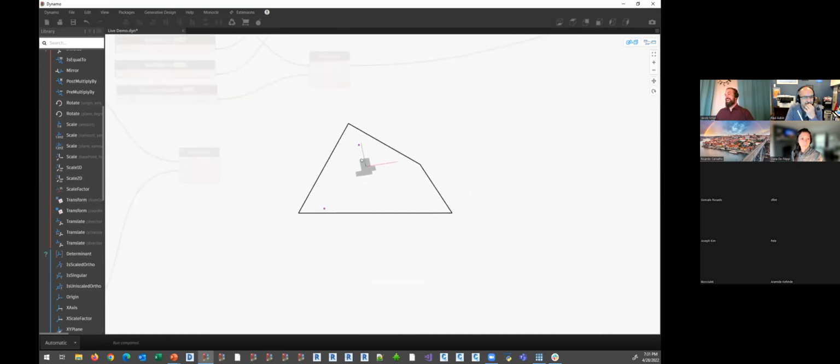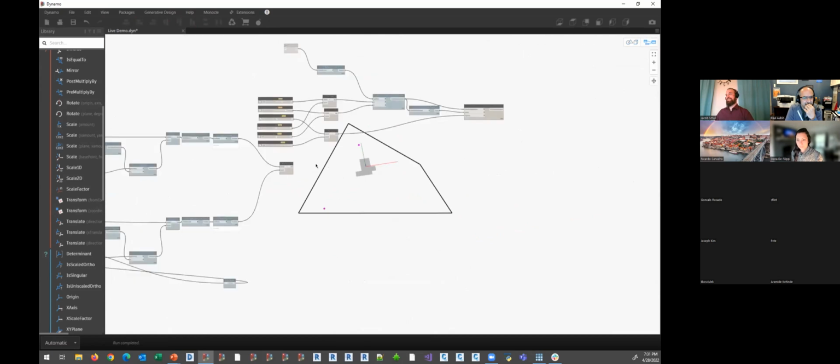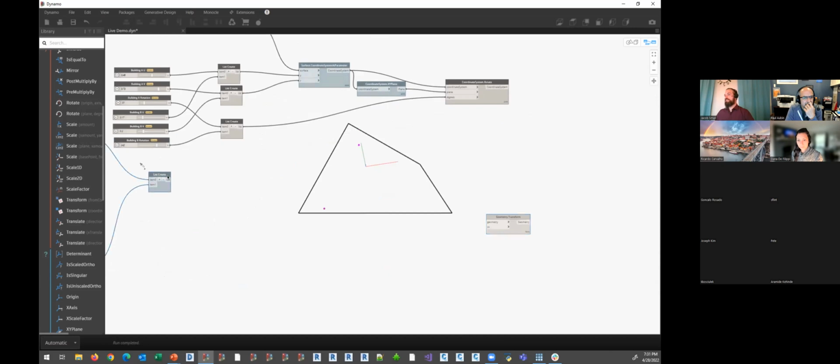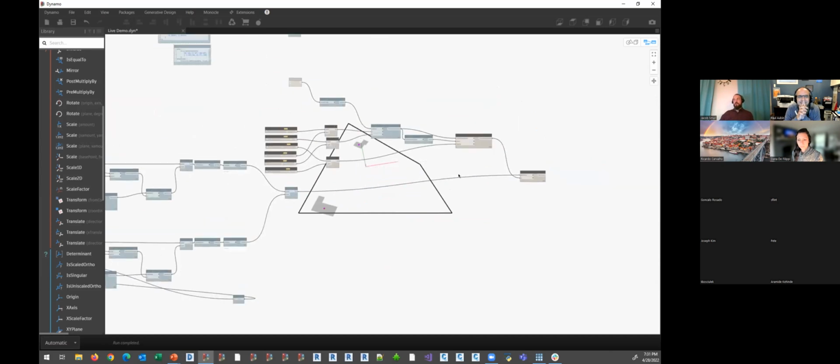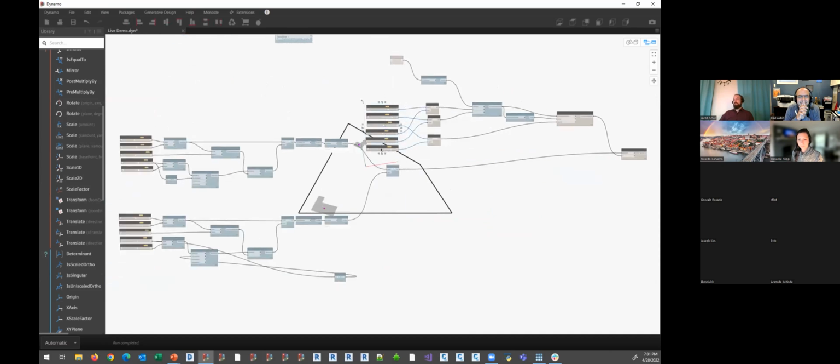So you can see I've got 2 coordinate systems, right? And I happen to have 2 sets of buildings. So geometry.transform once again. With my 2 different geometries, I don't need to worry about lacing because I've got 2 different coordinate systems. So now I can adjust the size of any one of these, adjust the rotation of any one of these, and adjust the location of any one of these. We've got a full parametric model that we built.